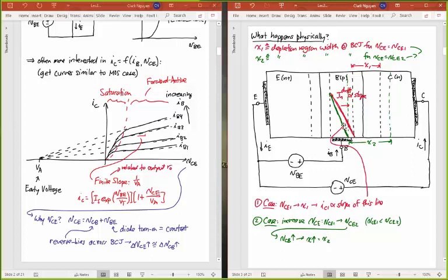And so I still have the case with X2 that my IC, which I'll call IC2 for case 2, still has to be proportional to the slope of the minority carrier distribution, which is this line right there. But you notice that that slope is larger. Because that slope is larger, this slope is greater than that slope.